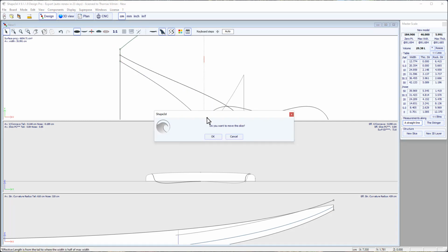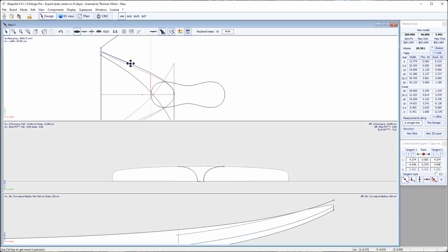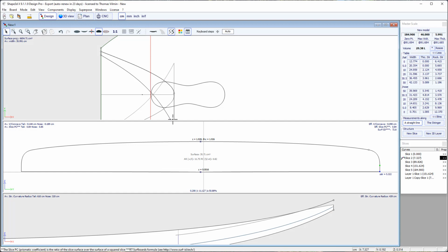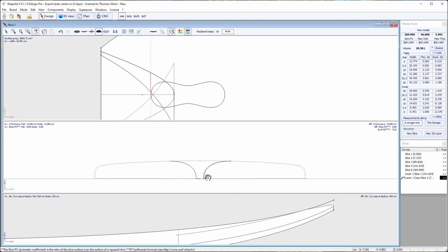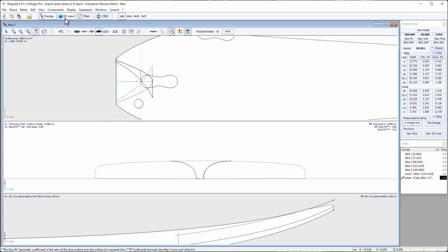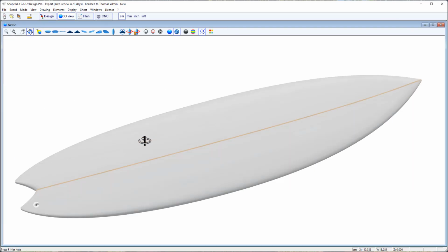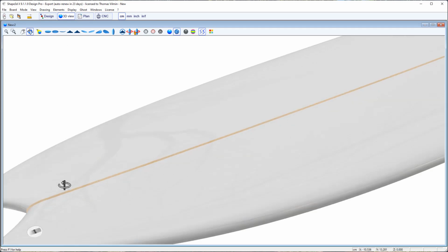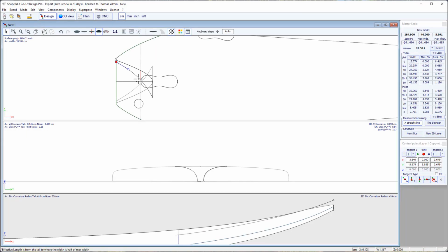we would make the inner side more like this. Move the slice here. And that's it. If you look at the 3D view, you have your swallowtail cut clean and easy to design. And of course you can choose the shape you want, something more like this.